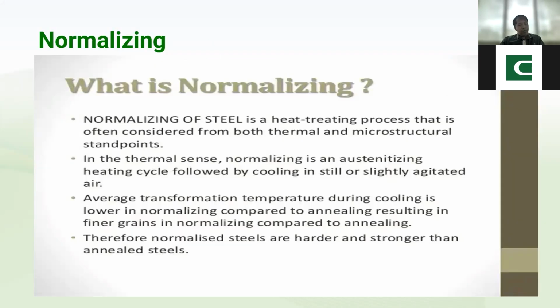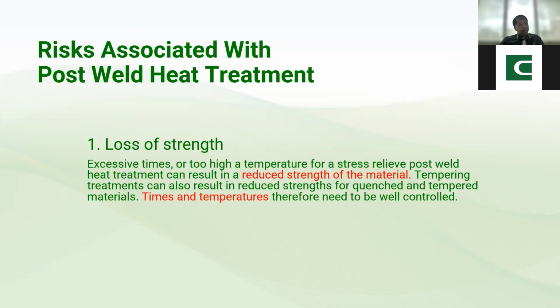Okay, so if you conduct post-weld heat treatment, make sure we follow the soaking temperature, no? Kasi if you exceed the soaking temperature, halimbawa soaking temperature mo 600 to 650, lumampas ka ng 650, there is a risk that you lose strength of your steel.